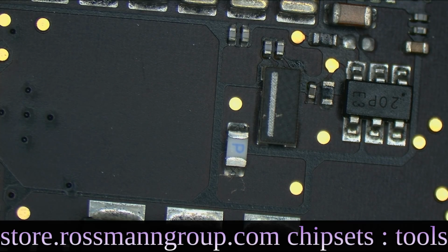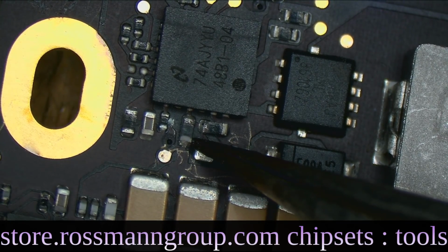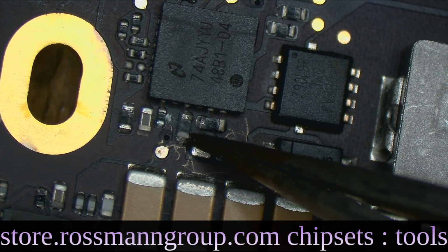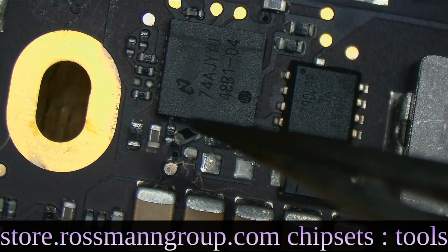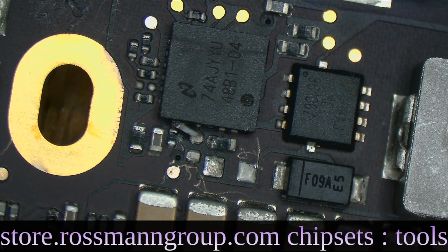So since the fuse is good, I'm going to take a guess that backlight is not working due to blown feedback. And I could probably knock that resistor right off the board. Okay, maybe not. I haven't been lifting as much at the gym recently. Ah, there we go. Took a little longer than I wanted. So we're going to replace that. And Paul's going to reassemble this because I don't remember how to. And then we're going to see if it has a light in the screen.